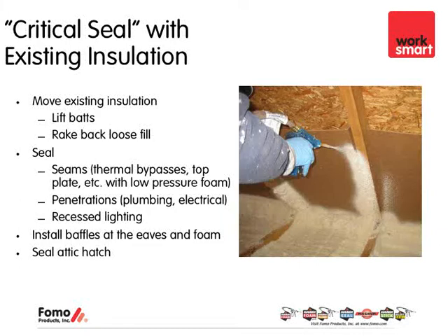Then the third that we're going to talk about is not critical sealing, but rather sealing the entire attic floor, what we would call more of a skim coat on the entire attic floor. This one provides a little bit more of a guaranteed seal because in case you happen to miss a few critical seal points within the attic, the entire seal of the attic will make sure that that is not the case. So I want to talk about all three of those.